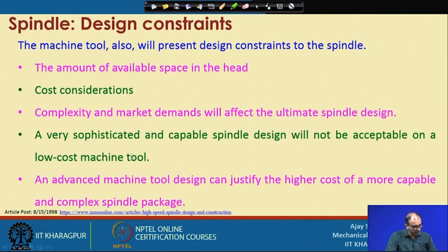So, first you have to find what the machine tool design is. If stiffness, vibration damping capacity and axis orthogonality are everything very fine tuned, then you can justify that whatever part you are machining there will be a high quality part.